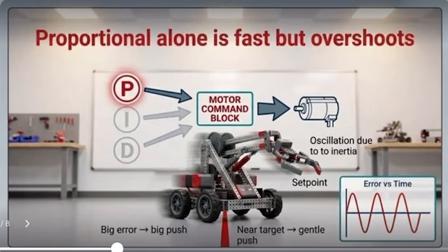That could be like upping your P by 30 or by 35. But let's say your error is small. That means you have to take it down a little. So a gentle push. So what I mean by that is let's say at 35 your robot is only oscillating a little. You're gonna have to put that to 37 or like 36 or even by 0.3. Like it takes a long time to get these things correct.